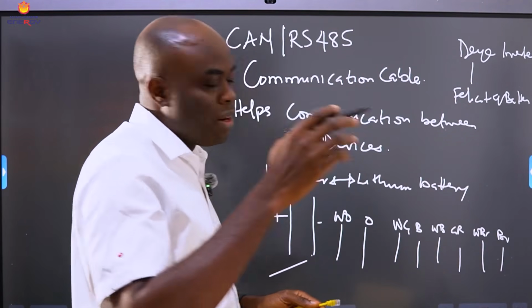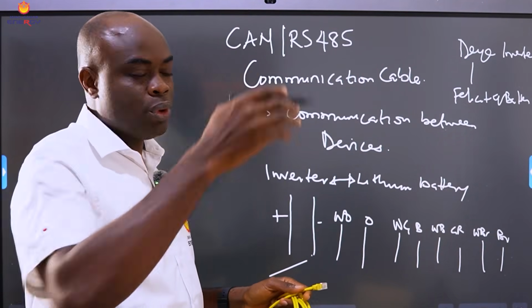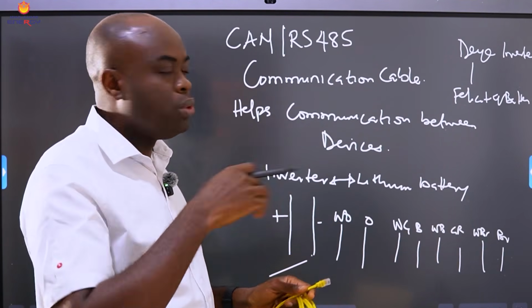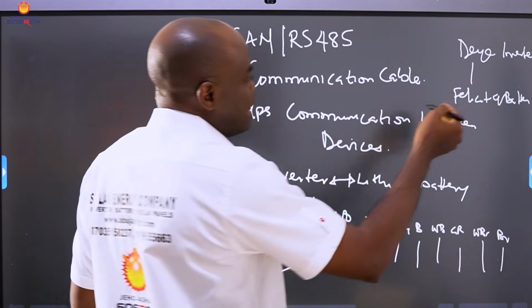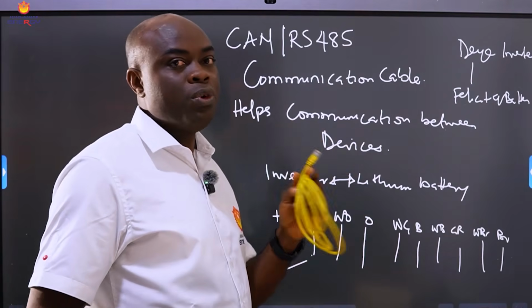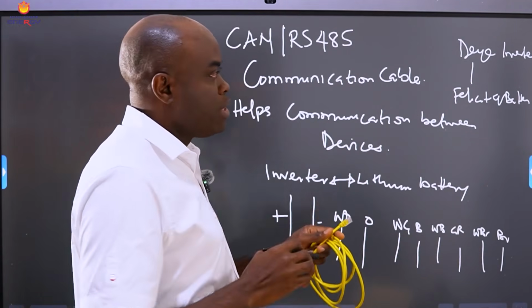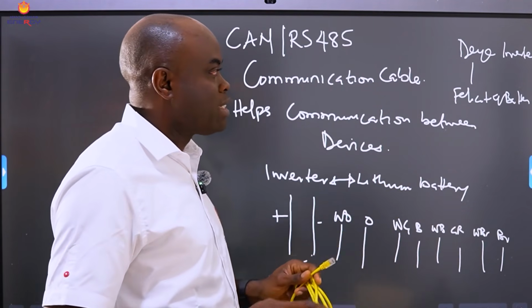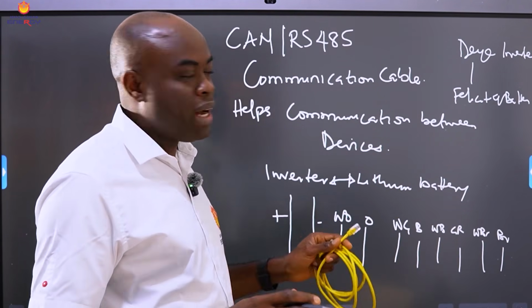It's from the RS485 protocols. There's a list of tables your manufacturer gives you that helps you to know the communication. The same also applies to other battery brands, which I won't mention. You don't use a standard; if you use it, it won't work. But there's where you crimp it, then you select a protocol that works with it. So with that, you have peace of mind that your battery is communicating.